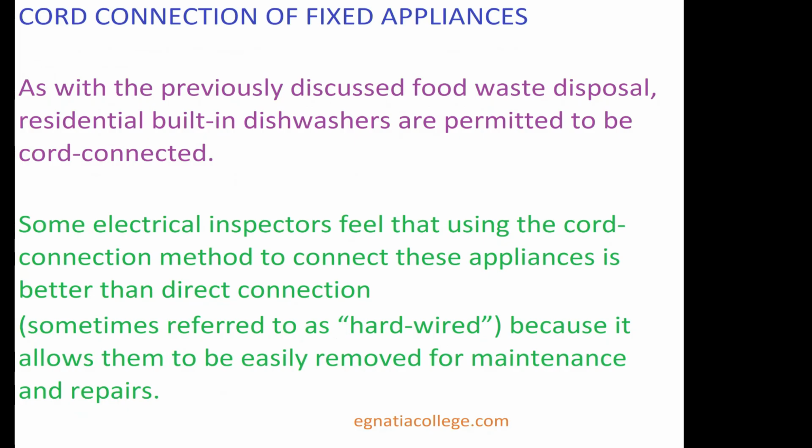Cord connection of fixed appliances. As with the previously discussed food waste disposal, residential built-in dishwashers are permitted to be cord connected. Some electrical inspectors feel that using the cord connection method to connect these appliances is better than direct connection, sometimes referred to as hardwired, because it allows them to be easily removed for maintenance and repairs.